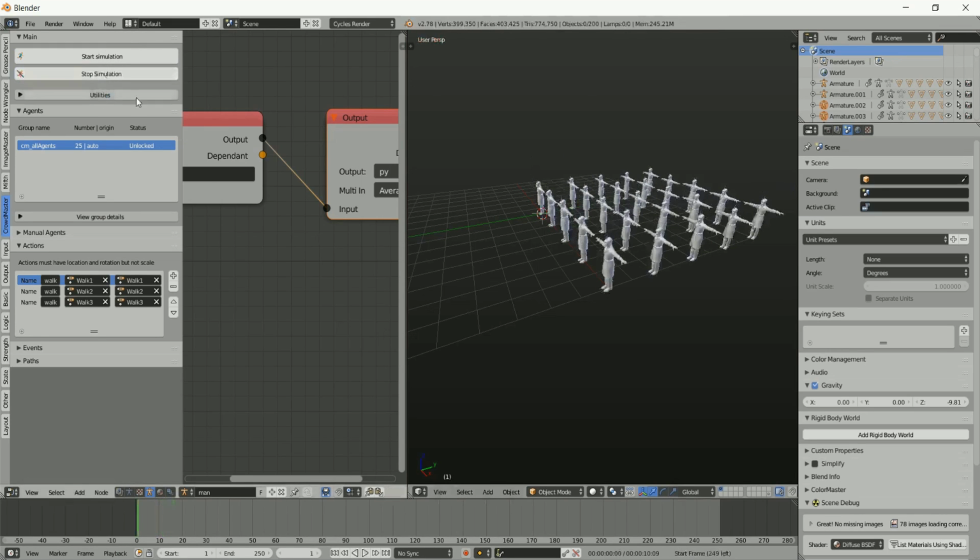And why is that happening? Well, that's because our rotation was not applied. So try to apply your rotation if you can. If not, you're going to have to do all this stuff like this to compensate for that. So in this case, change the positive y to positive z because they're rotated to look in the z direction. And let's hit start simulation.